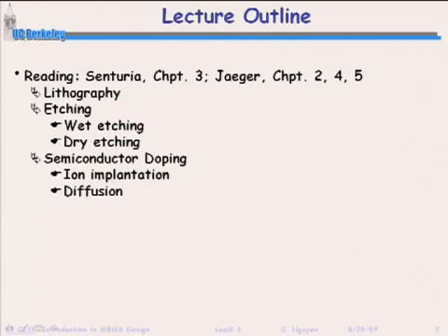All right, so lithography. What is lithography? This is a method for patterning massive numbers of features on a wafer. So you can pattern billions of devices, or more, today in just a few steps. This is the beauty of the whole silicon IC process. Wafer-level fabrication is all based on lithography.